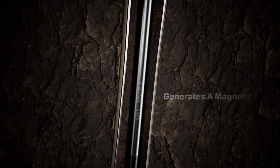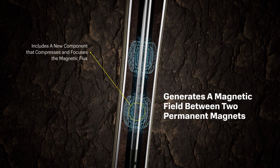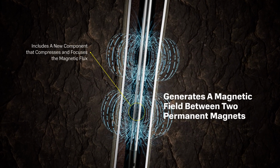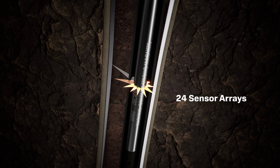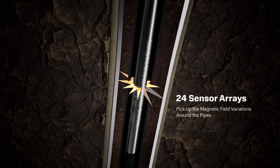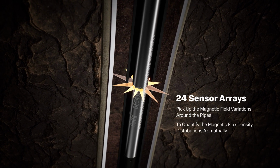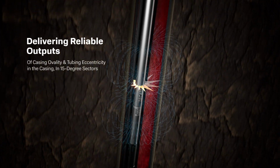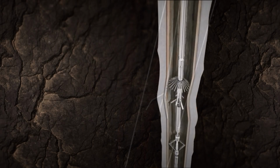The DEC tool generates a magnetic field between two permanent magnets and includes a new component that compresses and focuses the magnetic flux, pushing more of it to the casing behind the tubing. The tool's two 24-sensor arrays then pick up the magnetic field variations around the pipes to quantify the magnetic flux density distributions azimuthally, delivering reliable outputs of casing ovality and tubing eccentricity in the casing in 15-degree sectors.